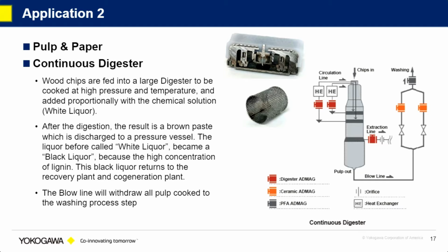I will also say that a lot of these technologies have the ability to do inline verification, meaning you can check the health, you can detect coating on the electrodes, you can check performance compared to the original factory delivery, and this product has that feature as well.